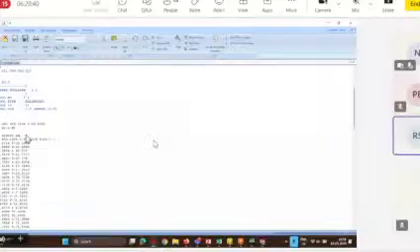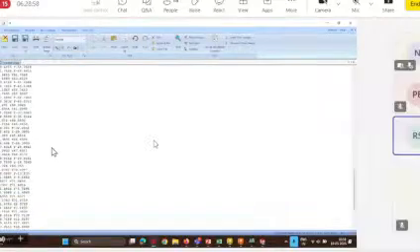So here I can write, at the beginning of 137, once it reaches over here, I can write M51, which is going to start the welding. And then I will keep on searching for the next Z0. So here Z0 is here only. So before that one, I can put another command, maybe M52.